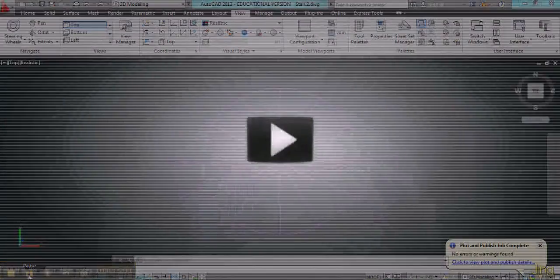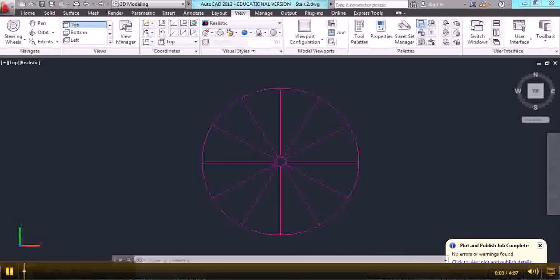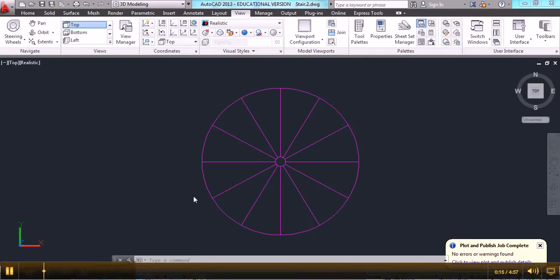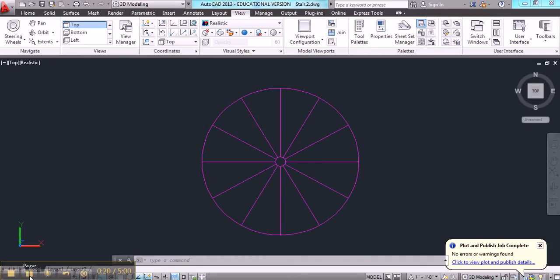In this first video on the spiral stairs, I'm going to show you how to make the treads that wrap around a center post. My recommendation is that you first draw the stair in plan view, like I have right here, using the criteria in the handout. Now I've drawn those on a layer that I'll then turn off, but you'll also want to start a layer called Stair and begin constructing the stair on that layer. So I've made it the current layer.